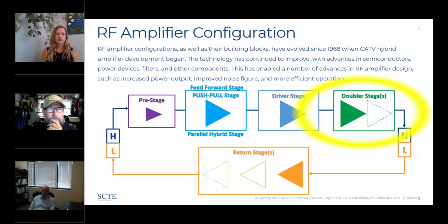The output stage today, as we know it, is a doubler block, and it uses a driver as a mid-stage block to support the high output levels required to overcome the coax attenuation at the higher frequencies. Recently, a pre-stage low noise amplifier has been introduced with a low noise figure to support the even higher levels that we need, while increasing performance as well.